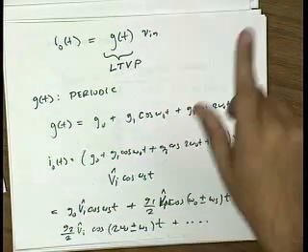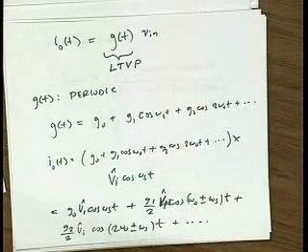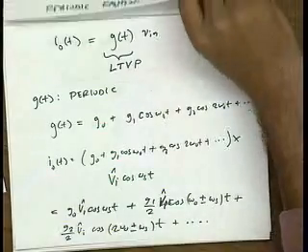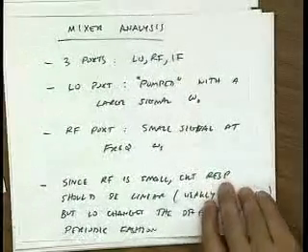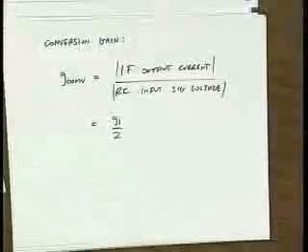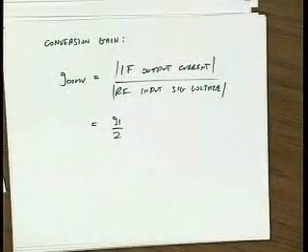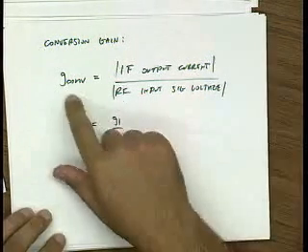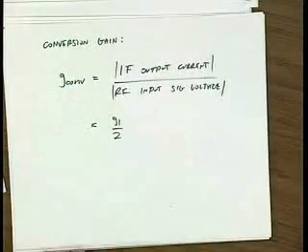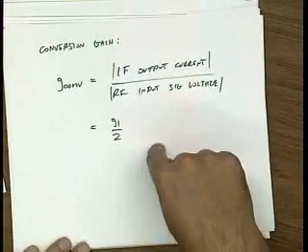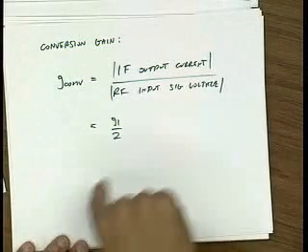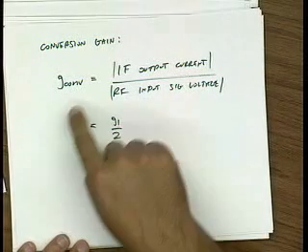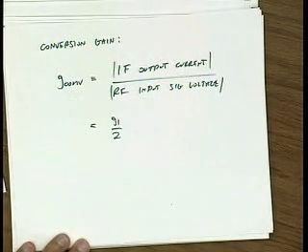Okay, that's a good question. Could you go back to the final slide with the conversion gain? Oh, just so I could look at it. That's G1 over 2? Yep. G1 is the first harmonic of the periodic LO. So G conversion, it looks like a transconductance between the input and the output. The difference, though, is that the input and output are at different frequencies. That's why we call it a conversion gain.